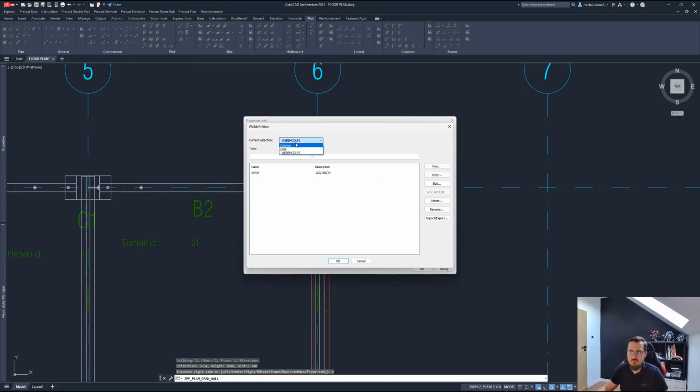There's a couple of levels for the standard that you have. There's the overall, say, common standard. So that's company specific, company wide. There's also local, that's one level below that. And the most compact standard is the project standard. Maybe your factory creates sandwich panels 30, 35, 36, 37, like every centimeter thickness, right? But for one project, you might just need 34s, or as in this case, or 40s, or just those two, and you can import those two. So it will not muddle your selection while placing those elements. For me, I'm just leaving it as is, sandwich panels thickness 34.